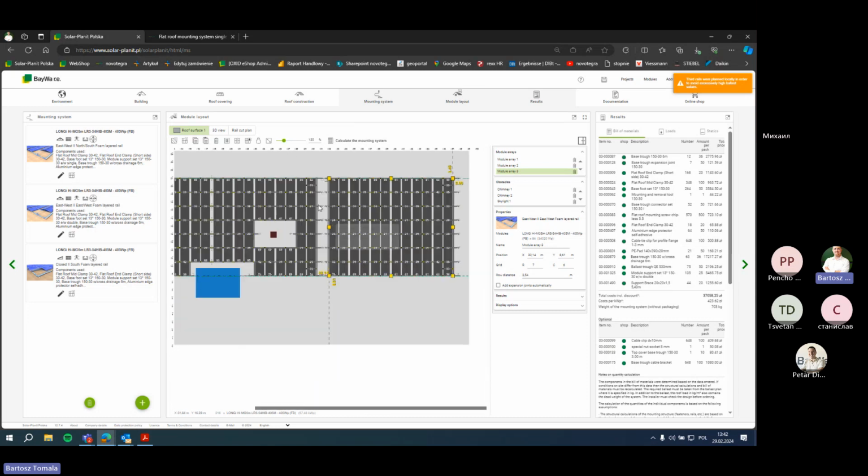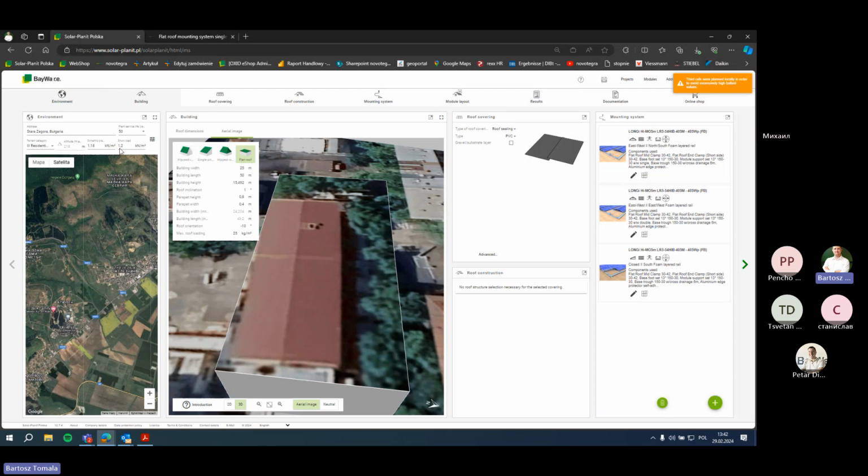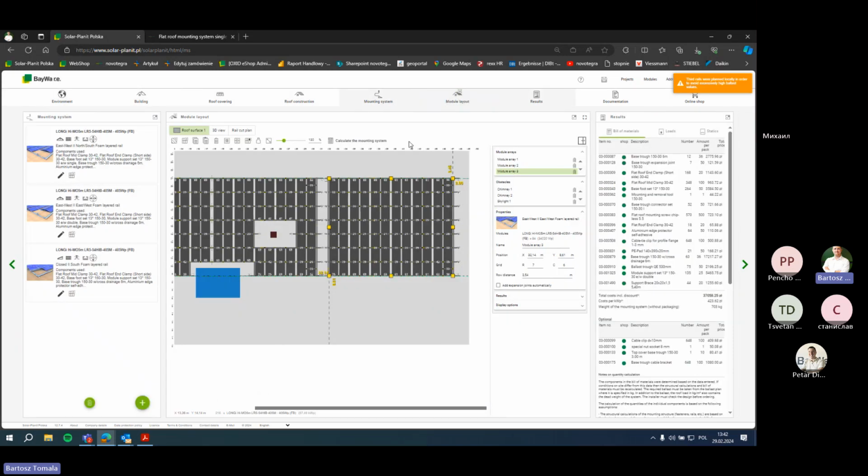But as I was talking about the module resistance and this module approval list, we could see the difference between the module strength is much higher than the datasheet says. And let's say these Longi modules which we have now selected, strength will be 1000 pascals, so it will be about 1 kilonewton per square meter. So the values in this location are higher. How can we deal with this?